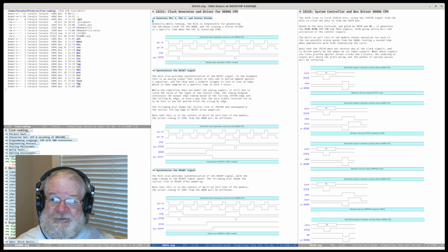And I was able to use those timing diagrams to derive precisely when these edges change, what the relative timing is, how long Phi 1 stays high and how long Phi 2 stays high, and the fact that they don't overlap, and the fact that between these two edges, Phi 1 dropping and Phi 2 rising, there could be a gap between them, but in practice there isn't, and that there is a gap here.